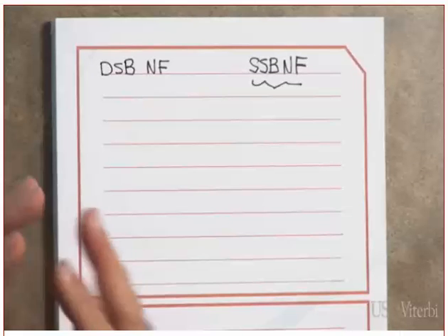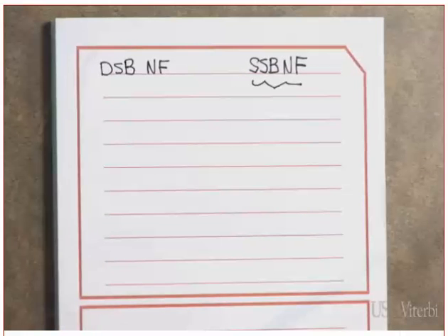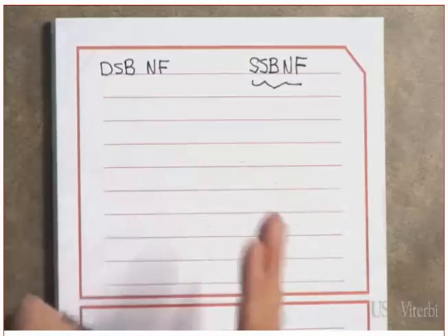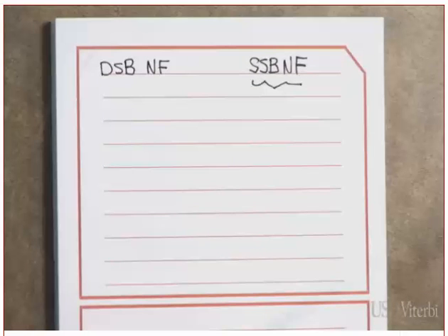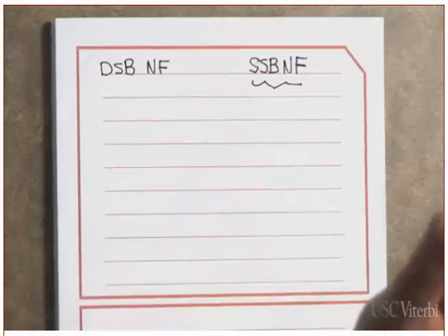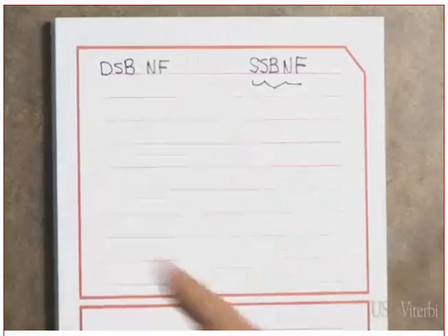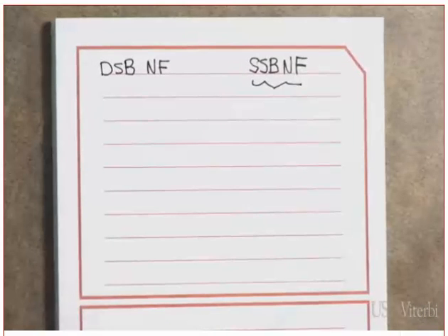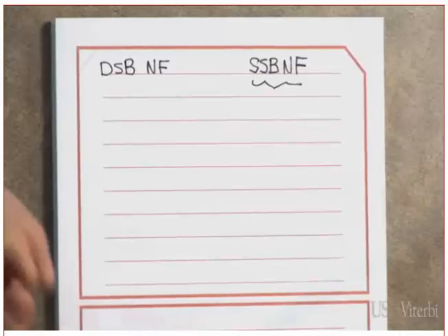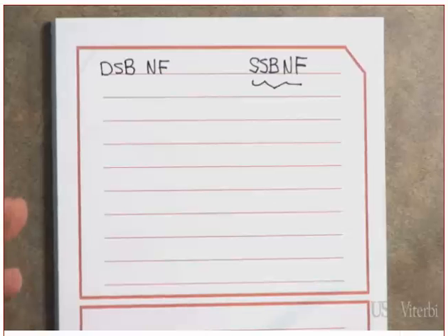Please listen to me. When we were talking earlier on this subject, we said that the RF frequency is displaced from the LO by the value of the IF frequency. Yes or no? Either the RF is higher than the LO, which we refer to as low side injection, or the other way around, we call it high side injection. What do we have on the other side?